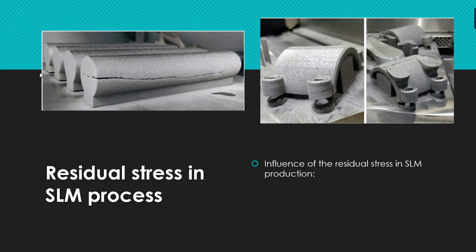As you can see, the existence of the residual stress will not only affect the dimensional stability of the component, but also reduce the yield strength, fatigue strength, and corrosion resistance of the component. How to reduce the residual stress in the laser additive manufacturing component without reducing its performance has been one of the focuses in the laser processing field.